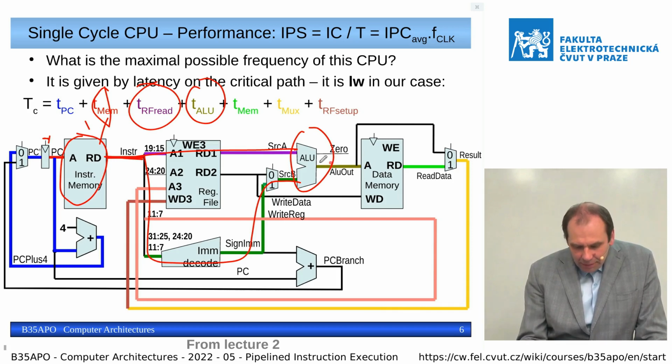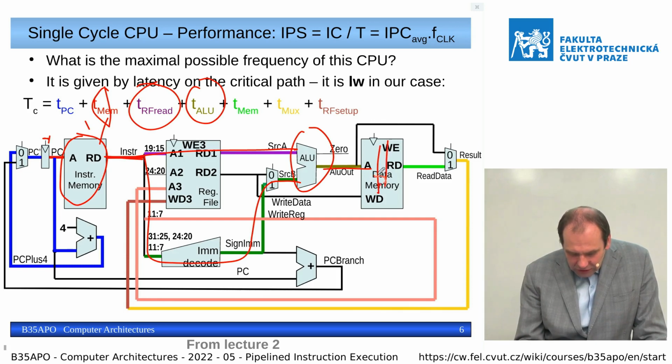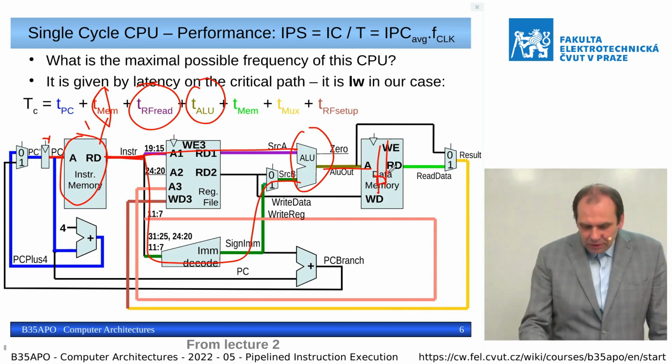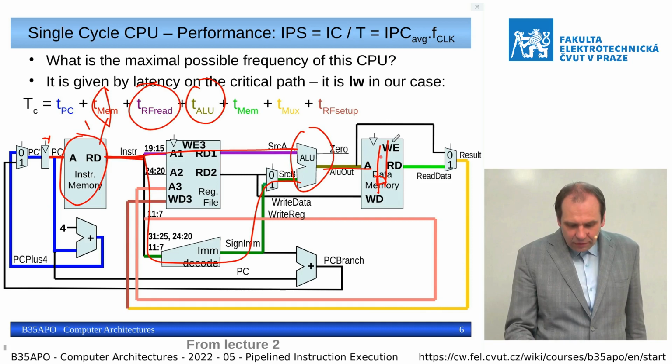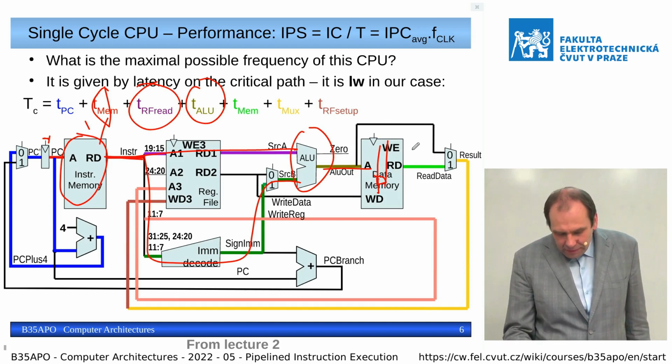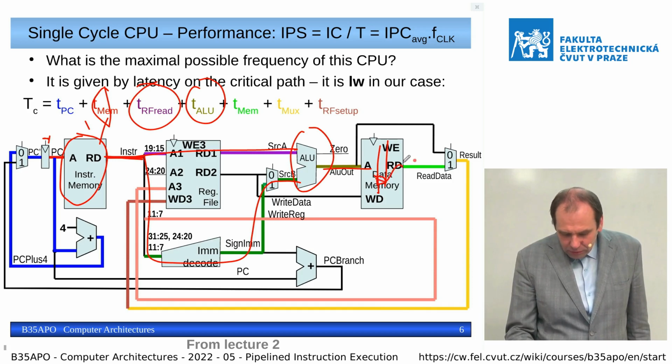Then in some cases we go directly to the write back, but for other instructions we set the address and need to wait until the actual location in the memory is found, basically when the decoder selects the correct word line and bit line and so on, and it is set to the output.